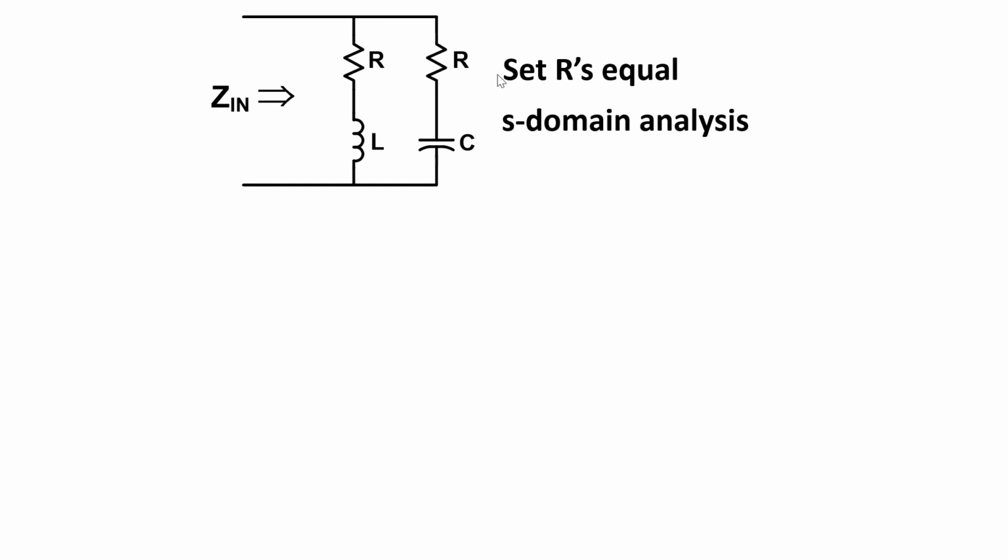Now, anytime I have an RLC circuit, one of the characteristics I talk about is the resonant frequency. One way of defining a resonant frequency is the frequency where the impedance of an RLC circuit goes resistive. By that definition, I'm going to show that this circuit, with the constraints that I present, is going to be resonant at all frequencies.